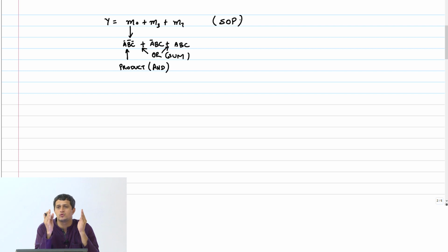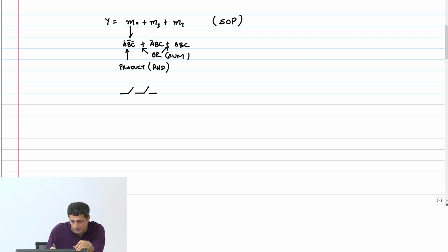The idea is now to take this and implement it in static CMOS logic, okay? So the point is, if I have any arbitrary switch, and I put two of these in series, controlled by signals A and B, then the signal X from here will go to the output Y when both A and B are closed, right?